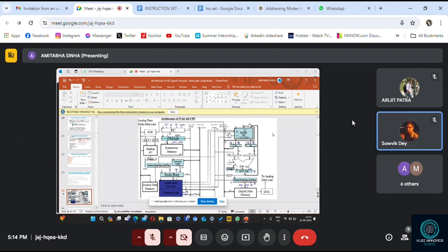Yes, sir. Now, instruction memory returns the data corresponding to that address given by PMAR. And that should be connected to what? That should be connected to the program memory data bus. What is the size of the program memory data bus? 32-bit. That's why this line is 32-bit.